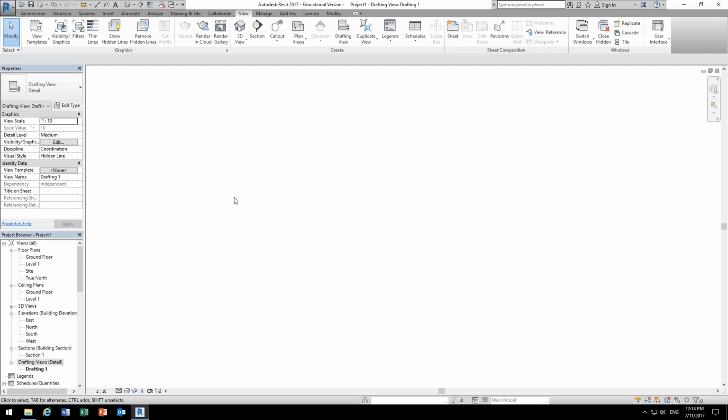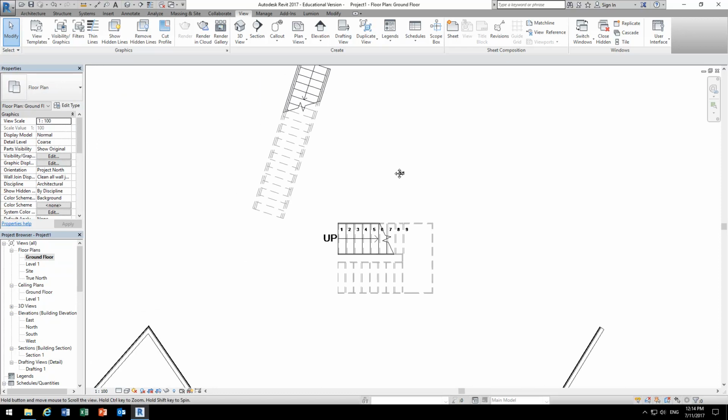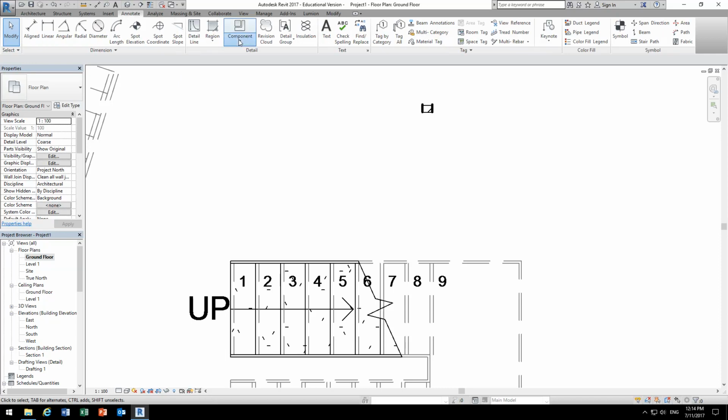And then what it can also help you with, finally, is repeating details, which is one of the great things in Revit that they've had from the beginning, but isn't used probably as much as it should be, because again, they're a system family, and a lot of people just don't know how to get them into their files. So if we go to here, Annotate under Component, you might have seen you've got Detail Components and then these Repeating Details.